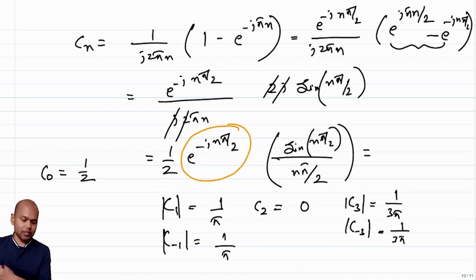And similarly, at n equal to 3, the phase is 3 pi over 2, and so on, right? If I shift the entire signal to the right or to the left, you are going to just add up the extra phases, and the only thing that is going to get impacted here is the phase, not the amplitude, right?